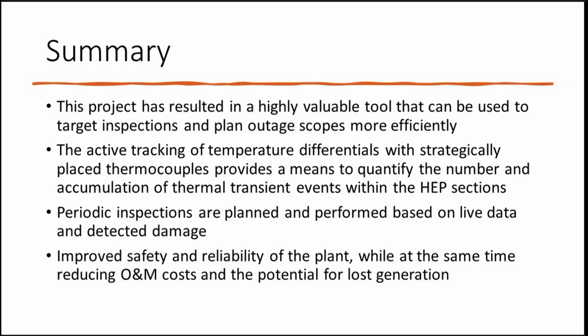So at that point, I guess there are two questions there. The physics base is really relating to what is happening, and that's where we're using the damage calculations. So it depends on which one you're talking about. Certainly for the creep damage, those pull in the pressures and temperatures and put them into an appropriate creep life correlation. And the stress is determined from previous redistributed analyses. The fatigue damage is then calculated, and there are a couple of different methods that we've implemented over time.